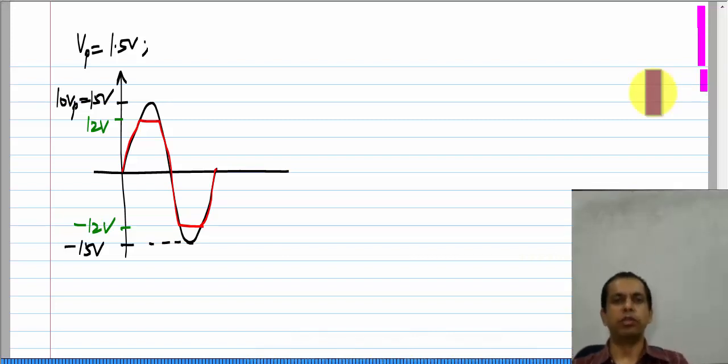It is very common to use equal values of VDD and VSS, that is, use symmetrical supplies, where the upper supply voltage is 12 and the lower one is minus 12, as I showed in these examples. But it is not necessary for them to be equal. You could have plus 12 volts and minus 6 volts. That will only change the limits you can have for V 1, V 2 and V naught.